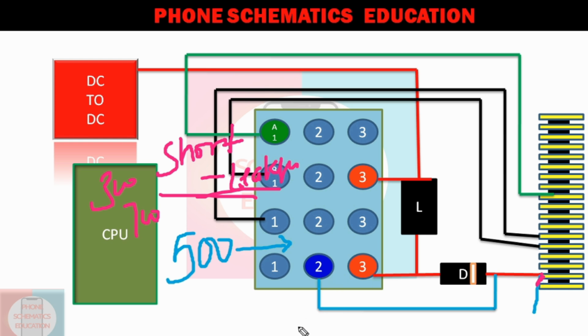Two types of bias, forward bias or reverse bias, right? If you did not get any value on a forward bias, like OL, or 1000 plus, and on a reverse bias you get 500, that means this line is connected properly. Okay, that doesn't mean there is no other problem on this circuit. For this testing, you can say this line is okay.